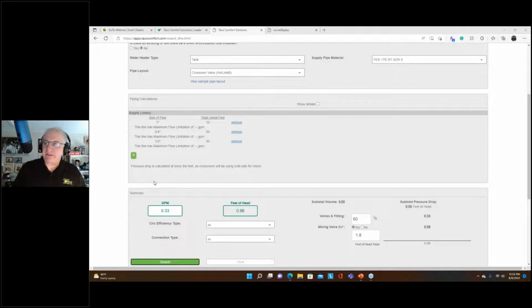Well, how do you know what their schedule is? Well, we just put it on in the morning and the afternoon and that's it. Or we ask them, which is good enough. A lot of other contractors just give the homeowner the instruction to say, you know your schedule, you set it up, which is inviting trouble because those things aren't that intuitive to set up. So having them set up appropriately to run when you need them to run is always a challenge.